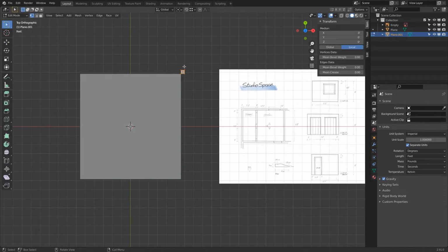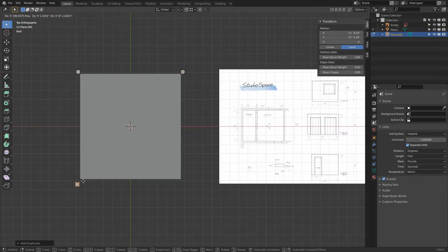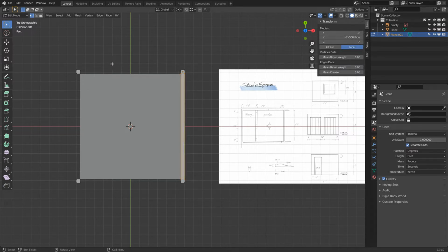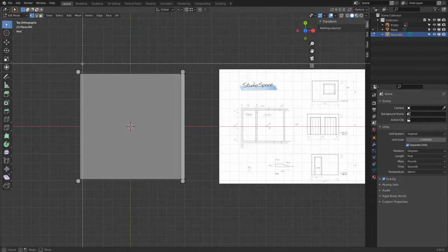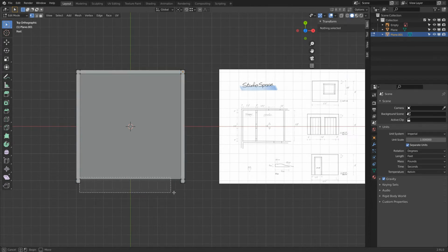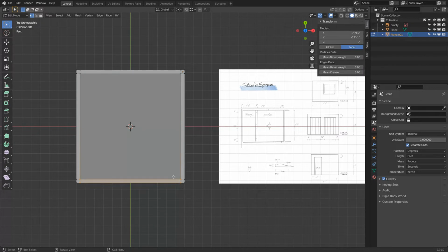Okay. Then we can go into edit mode. And I do the following. Shift D, bring this over. Snap, Shift D, bring this to there. G and snap, Shift D, bring this to there, G and snap. You see how I put actually these corner pieces to there. And then with B, I can select all those, and F, fill this, A, deselect everything, B and F, A, B, and F, A, B, and F. There. Super easy, no?